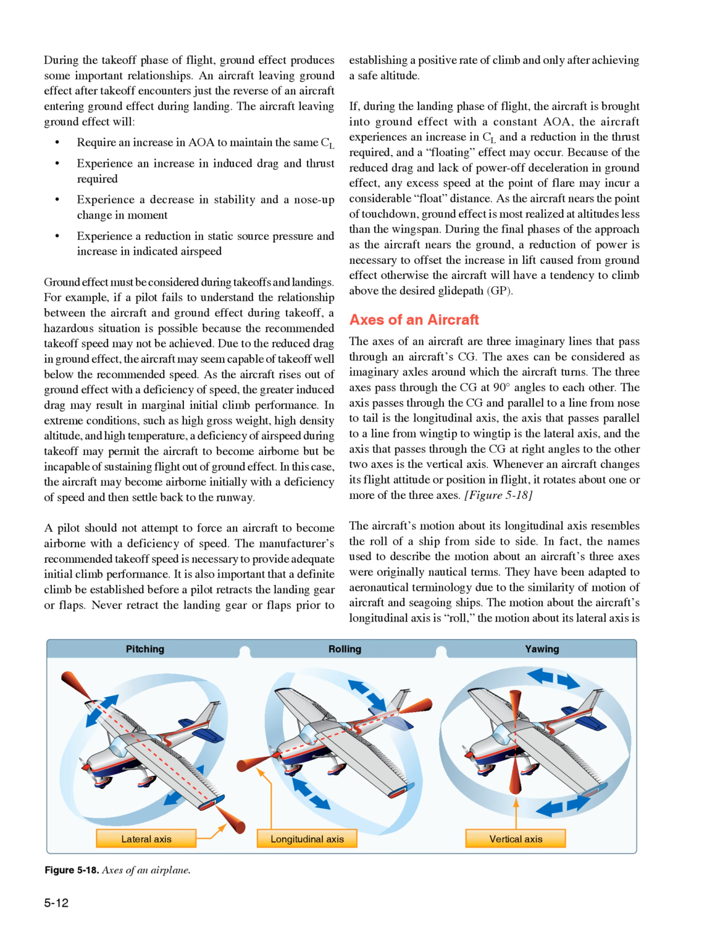During the takeoff phase of flight, ground effect produces some important relationships. An aircraft leaving ground effect after takeoff encounters just the reverse of an aircraft entering ground effect during landing. The aircraft leaving ground effect will require an increase in AOA to maintain the same CL, experience an increase in induced drag and thrust required, experience a decrease in stability and a nose-up change in moment, experience a reduction in static source pressure and increase in indicated airspeed. Ground effect must be considered during takeoffs and landings.